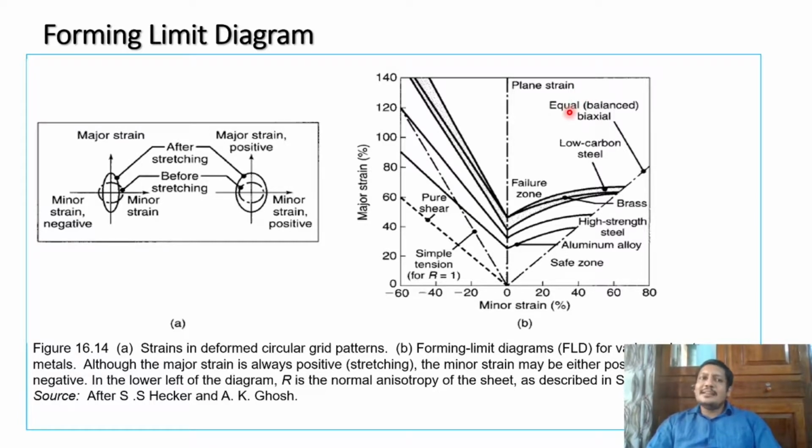For understanding, this is how the forming limit diagram is drawn, and these are the areas where failure is happening. These are the safer sites. According to that condition, thickness is a parameter. Based on the thickness, the curve is going to vary, as we have seen. So accordingly, you can choose different materials for deforming or forming operations.